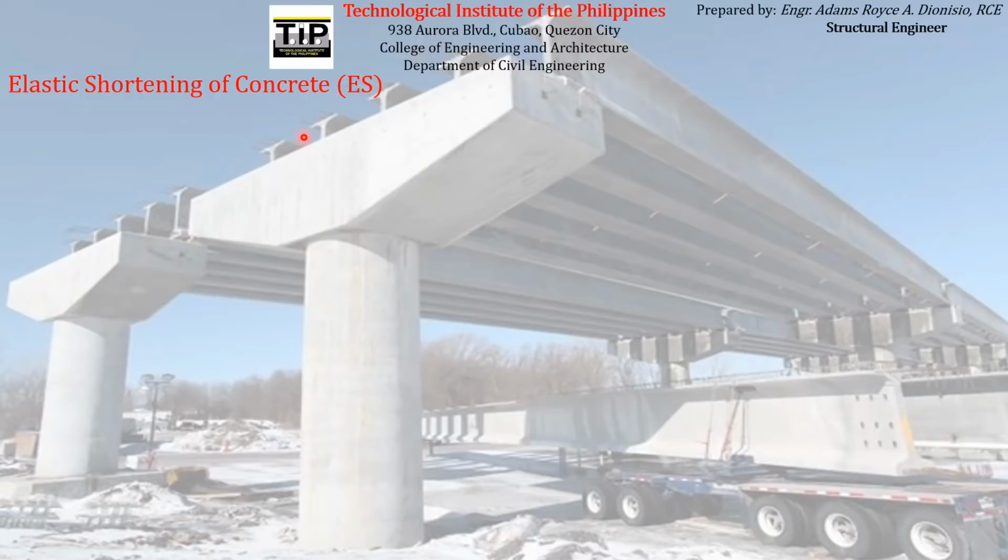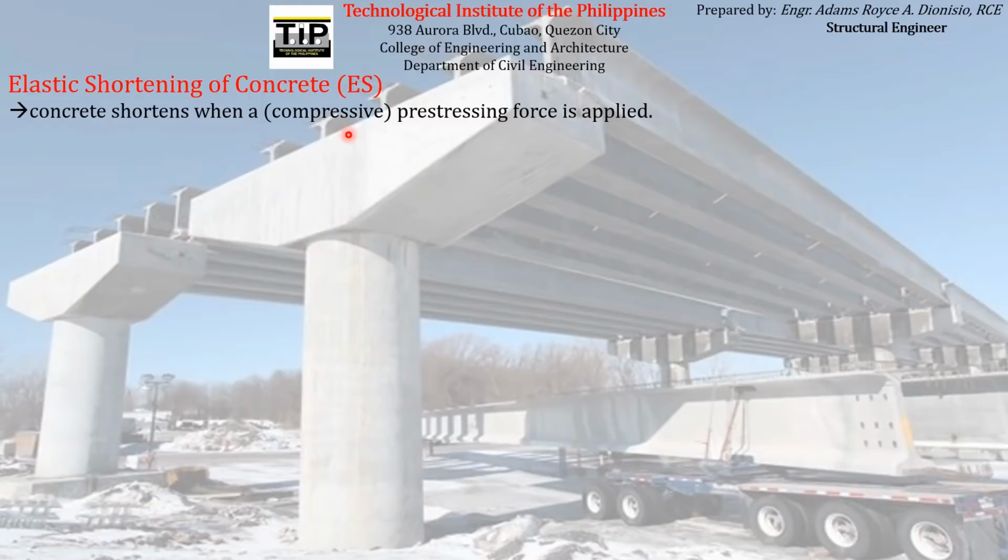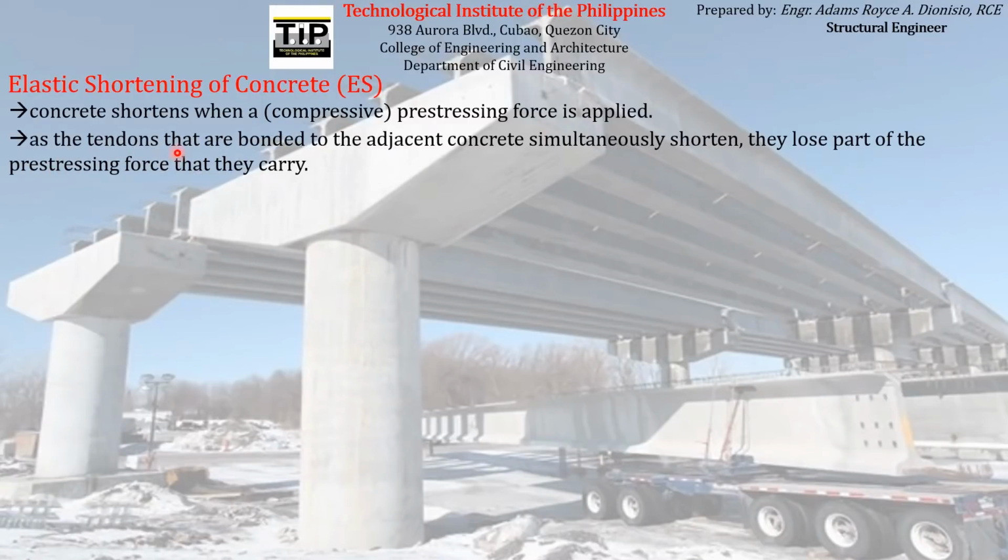So what is elastic shortening of concrete? Concrete shortens when a compressive prestressing force is applied. As the tendons that are bonded to the adjacent concrete simultaneously shorten, they lose part of the prestressing force that they carry. So that is the main reason why prestress loss occurs when the concrete experiences shortening.